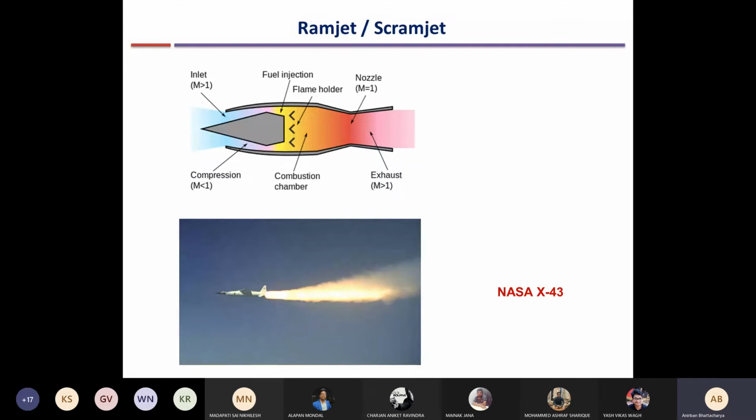What is the main advantage of a jet engine as compared to a rocket? So you won't carry any oxidizers. Correct. Right? So the weight will be much reduced, because for a jet engine you are just using ambient air. For rockets, you need to carry the oxidizer. So the overall weight of a jet engine will be much reduced. So only for the starting part, a rocket is used, then the jet engine takes over. And these, till now at least, have been only used for military applications, like operating missiles and for prototypes, but not actually for any aircraft.